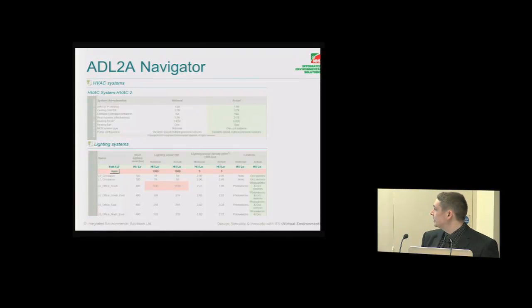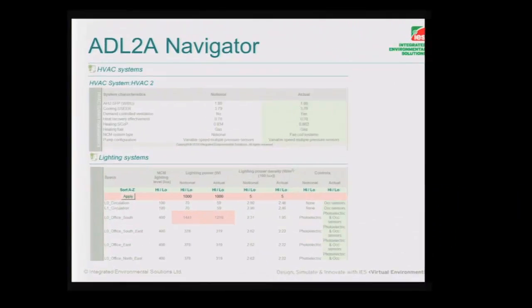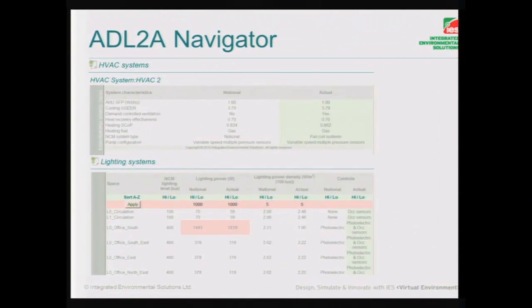Also, we've got in the end section a set of controls. So in the 2010 notional building, we started implementing photoelectric controls into probably the majority of activity types within any perimeter spaces within the building. So again, we're now in a position under 2010 methodology where just to equal the notional building, not only have we got to have very efficient lighting fittings in place, but we've also got to have photoelectric dimming controls in them, and that's again just to keep up with the notional building.